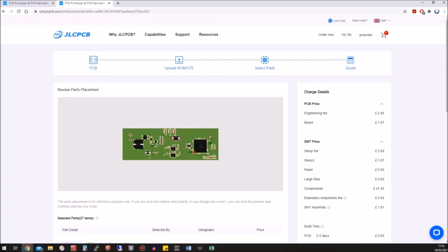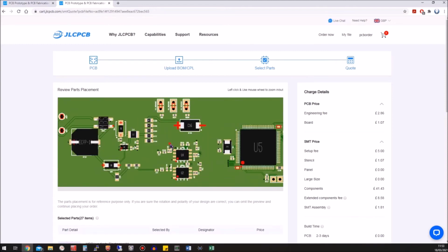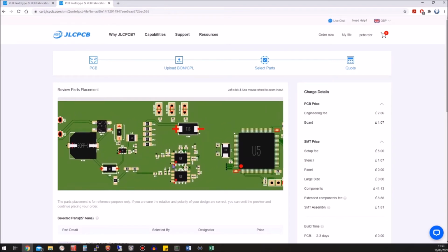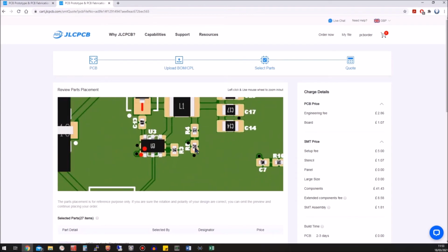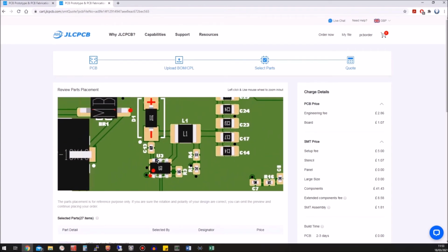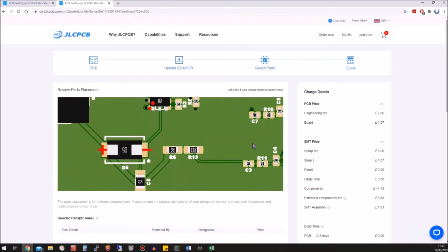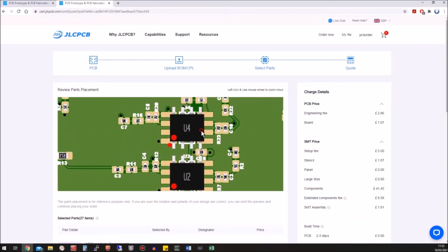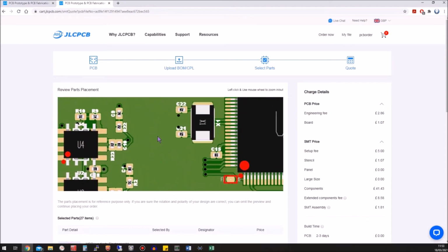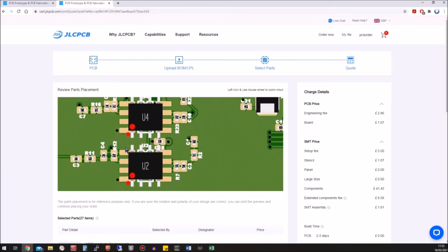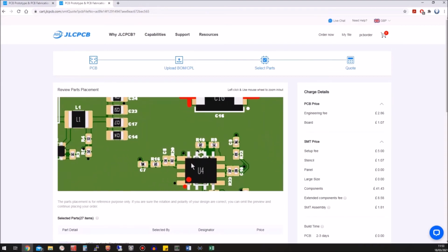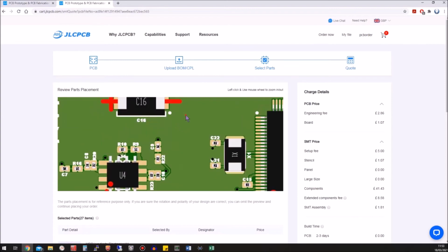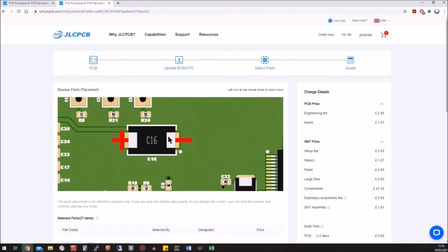This can be the most tedious step, because various PCB CAD packages have different orientations for their components, so you may find components 90 degrees or 180 degrees out of position. You see there are some here. Resistors don't matter, but polarized components like diodes, electrolytic and tantalum capacitors and IC chips will not work if placed the wrong way round. If a component is misplaced by 90 degrees, that's usually easy to spot. But take extra care to make sure polarized components haven't been misplaced by 180 degrees. This is easy to miss.